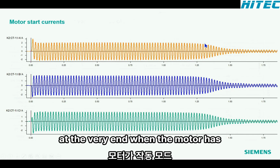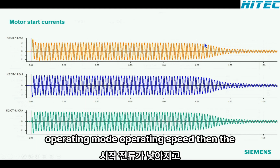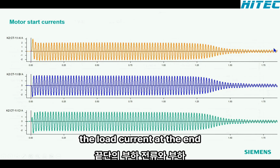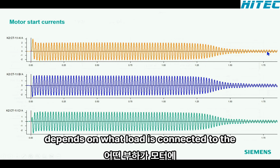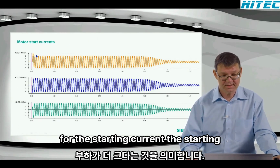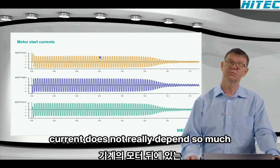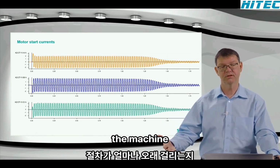And at the very end, when the motor has almost reached operating speed, the startup current goes down and I get the load current at the end. The size of the load current mainly depends on what load is connected to the motor. That means the bigger the load, the bigger the current. That's clear. Whereas the starting current does not really depend so much on the load which is behind the motor on the machine.